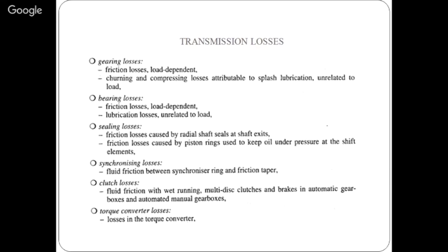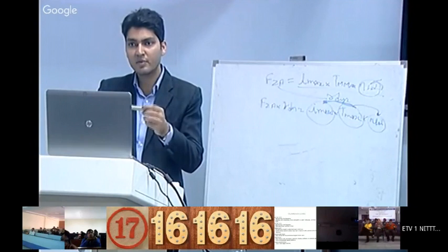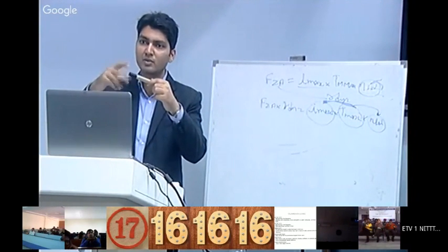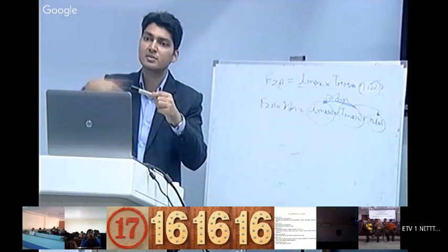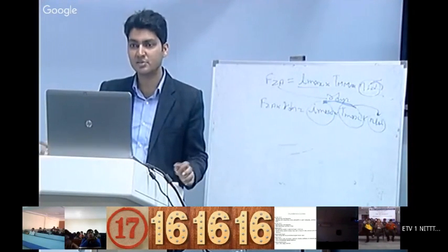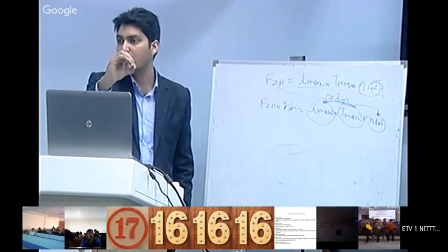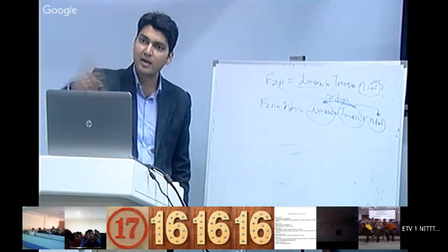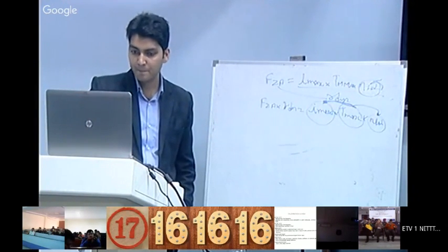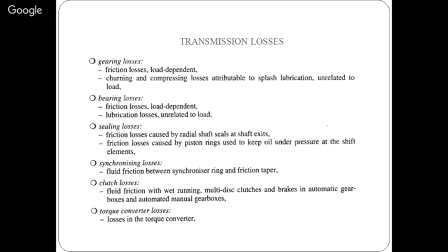Suppose this is a marker, this cup is tight. When I rotate this cup, it will consume a force. This is a loss. Otherwise, if it is a radial roller bearing, free rotating, that will consume less force. So in taper roller bearing, there are certain cases in which forces are introduced. The sealing losses: when we seal a particular shaft, it again contributes to losses. The synchronizing losses, the clutch losses, torque converter losses.